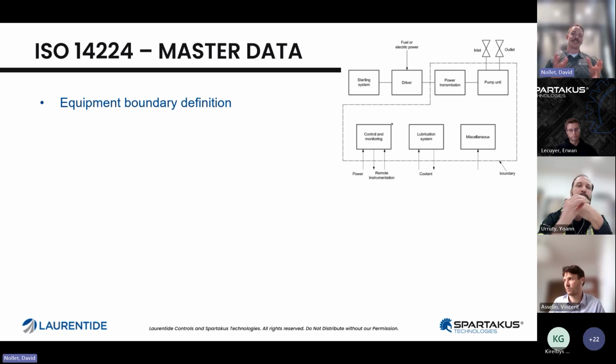And I'll say here that while this standard is a very good guide, I do not believe that it is complete enough, detailed enough to be something that we can just easily read and apply. It's a good guide, but there's maybe a little bit of precision that we need to add, and we might not agree with it everywhere. Like for instance, here, I have a pump in the image that's shown here, and the standard indicates that my motor should be separate outside from the boundary of that pump's equipment unit. I'm not sure I would do it that way. So there's some interpretation that goes into it.